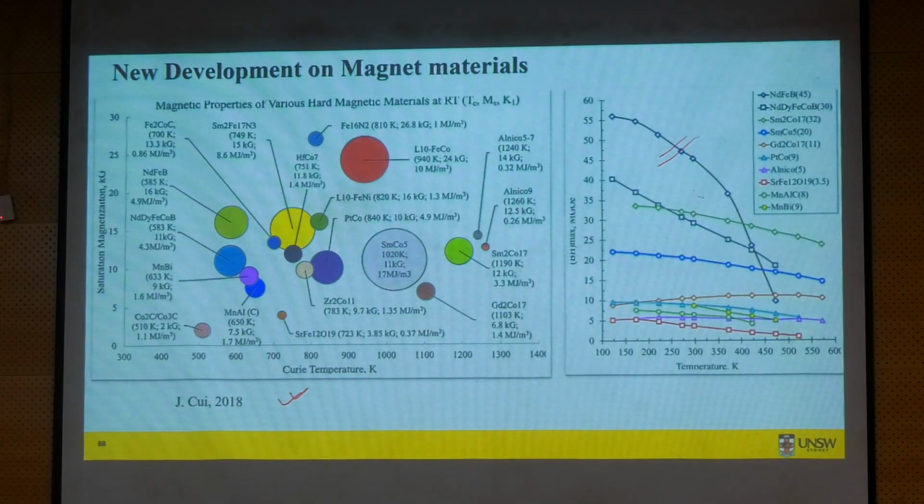The most recent designs people are trying to do use this type of material, and they try to see what changes the designs will require if we go for these magnet materials instead of neodymium iron. Those designs are known as rare earth free designs: not using rare earth at all, but they still use magnets, rare earth free magnets.